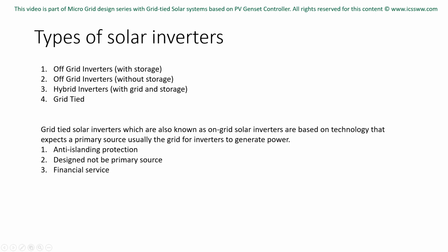Let's take a quick review of various types of solar inverters and their source requirements. There are inverters which operate in island mode. A solar inverter or a bunch of solar inverters that can generate power directly from sun without grid are assumed as inverters working in off-grid or island mode. In such a scenario, you have your own mini power plant which is independent of grid. These inverters usually have battery storage tied to them. The battery backup charges or discharges per the load demand.